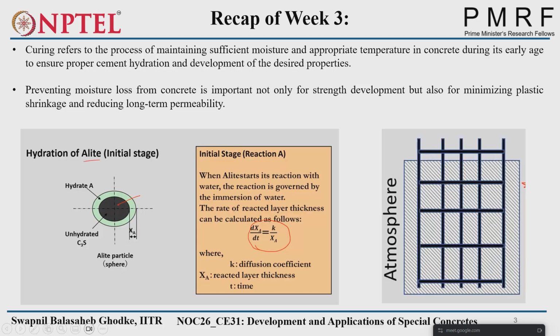No, because there is a difference. Water will not directly contact the core; the external water we are providing, the water curing compound, will be only here. Another thing is that moisture will evaporate easily from the surface, but if it has to evaporate from the center of the core, it has to travel this much distance, right? So there is a difference between the properties of the concrete on the surface and the core. We have to keep in mind that it will not always be the same.